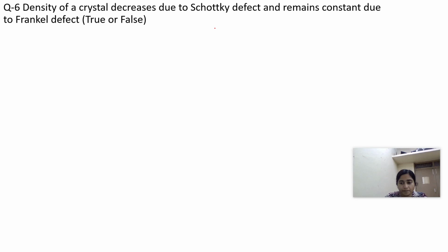Schottky defect is a type of point defect in the crystal. Normally in ionic crystals, the defect forms when oppositely charged ions leave their lattice sites, creating vacancies. These vacancies are formed in stoichiometric units to maintain the overall neutral charge of the ionic solid. The vacancies are then free to move about as their own entities. This defect will decrease the crystal density.